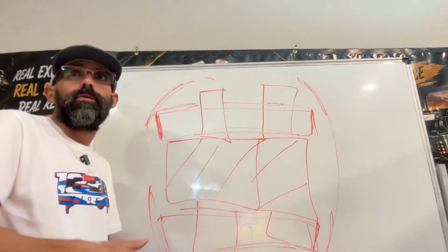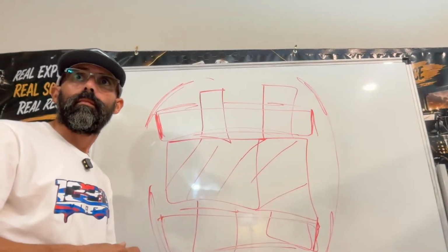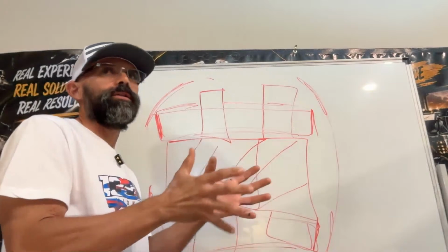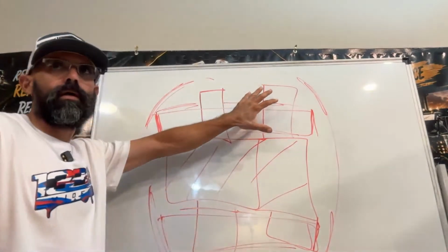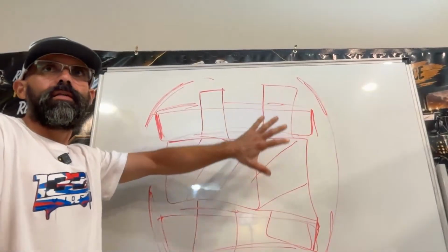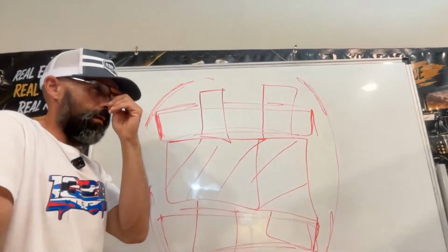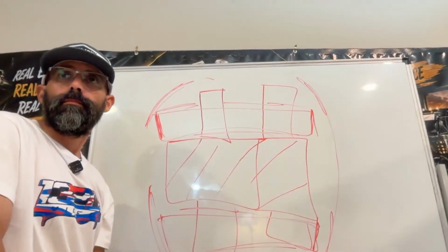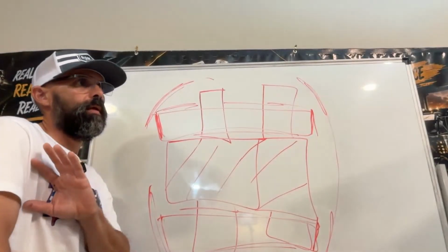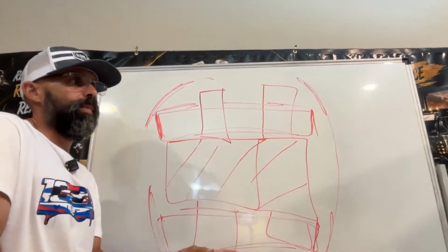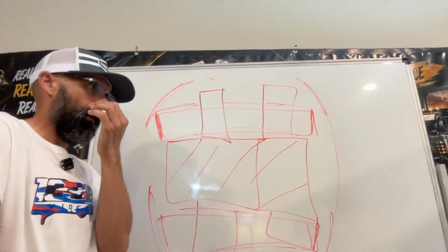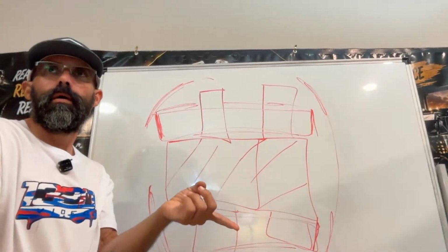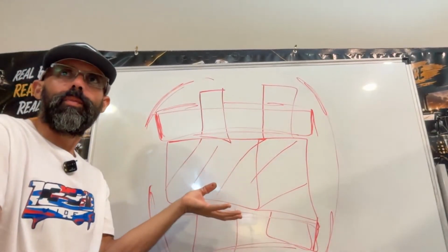There's nothing that I can do. Trying to mix used parts with new parts, especially on an aluminum gear pump housing like this one, you're gonna waste time and money. All the money and time you're gonna spend trying to make this work is gonna cost you more than getting a new pump and throwing it there.